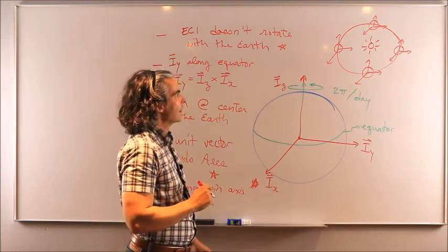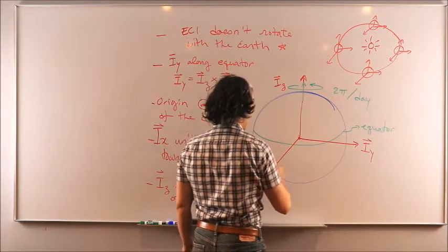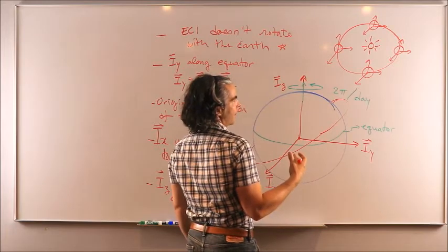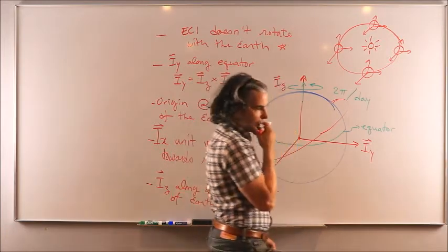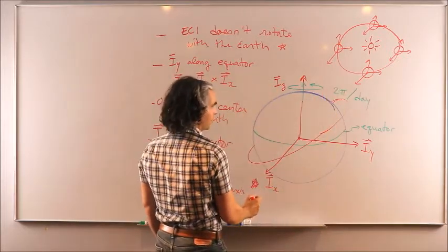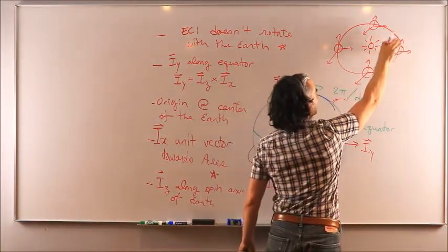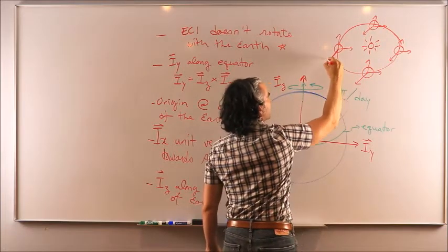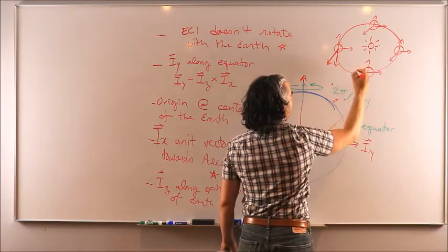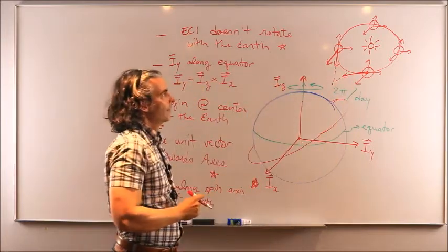Yes, it does move, but the orientation of the frame with respect to the Earth, about which our spacecraft is rotating, is not relevant. Say, okay, but then I don't understand. If that reference frame is supposed to always be pointing at the same star, which is way out there, how come this reference frame is not rotating with respect to the Earth to make sure that this vector points at the same star out there? Shouldn't it be rotated like that here and then moving upward here to ensure that we always point at the same star? The answer is yes.